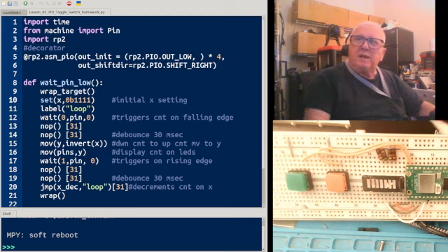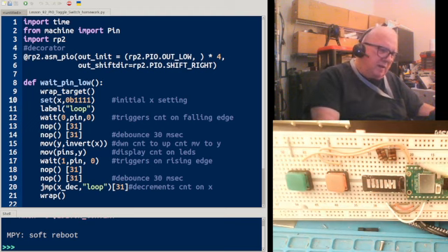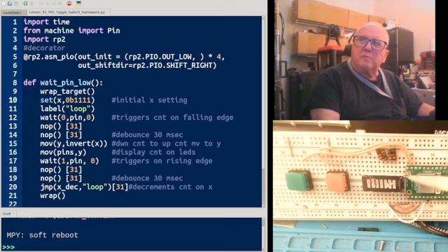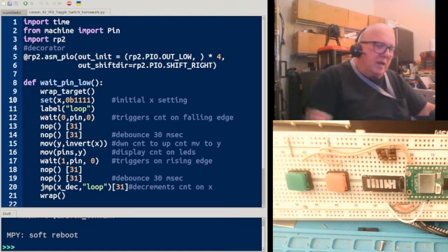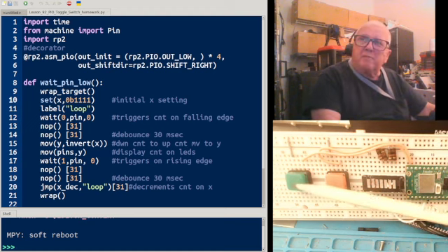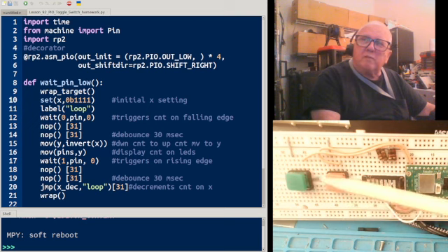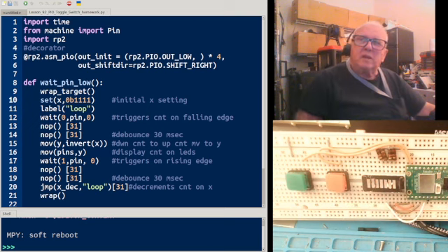If you look down here, you'll see I got the Raspberry Pi Pico. I have a bar graph for the LEDs. It's a lot easier to deal with those. And then I put 10K resistors in series with them to kind of keep the glare down. I'm using the green button for this software. The red button is not being used.